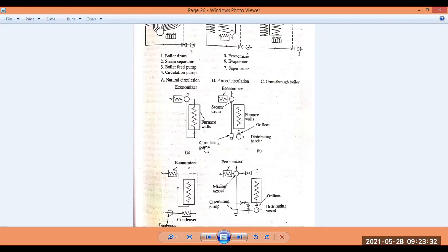First, the feed water is coming in at high pressure. It goes to the feed water heater itself, from which it comes to the economizer. You see here, it comes to the economizer and then leaves saturated or as a two-phase mixture of low quality. Thus it enters the drum.